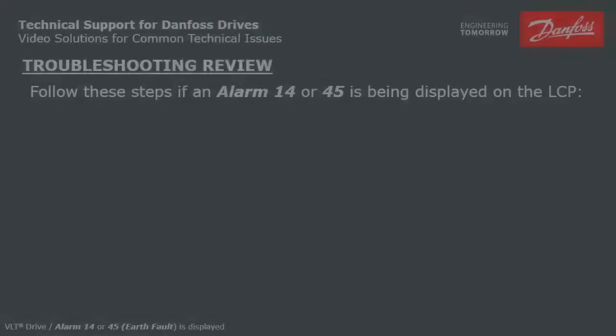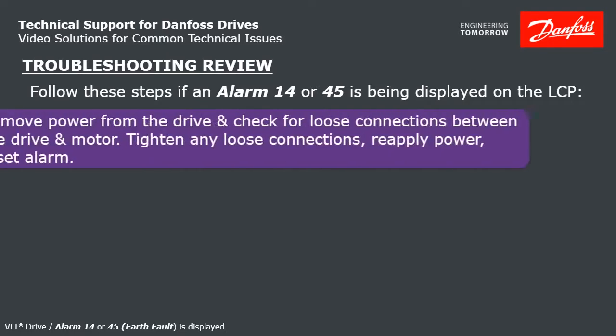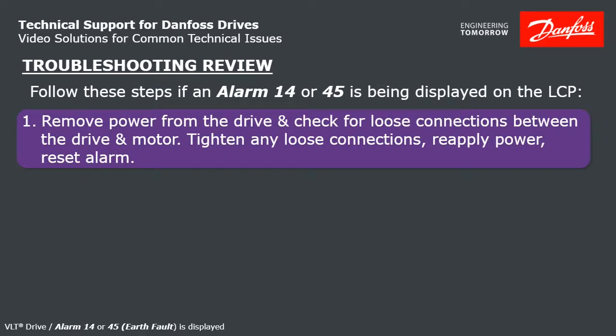Thanks for watching. Hopefully this video helps you in being able to efficiently solve your problem. As a review, here are some steps to take if an alarm 14 or 45 is being displayed on the LCP. Number 1, remove power from the drive and check for loose connections between the drive and motor. Tighten any loose connections, reapply power, and reset the alarm.